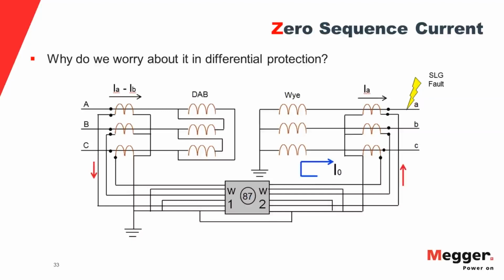So how do you eliminate this zero sequence current to not have any misoperation from differential? The simplest way to eliminate zero sequence current is to have Y connected CTs on the side of delta connected winding and vice versa. This would eliminate the zero sequence currents entering the relay in numerical way, and there would be no zero sequence currents going through the operating coil.